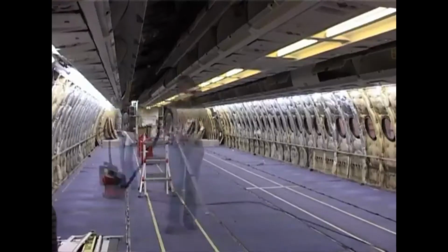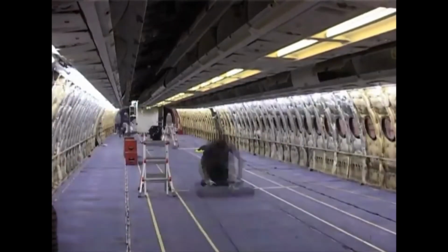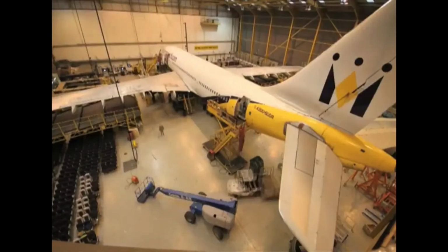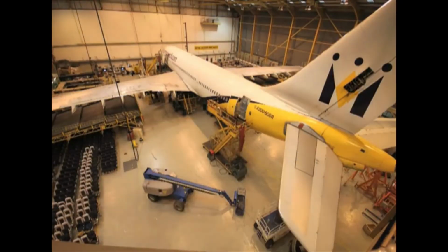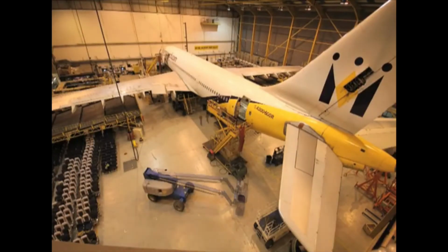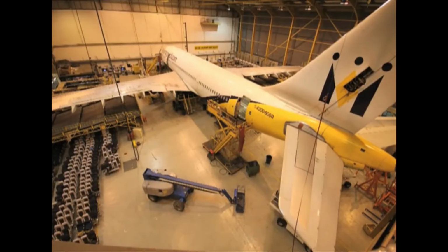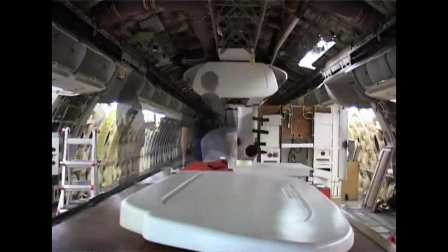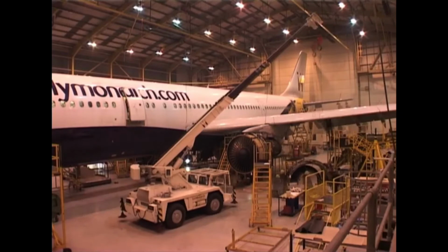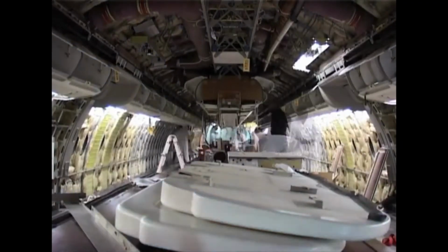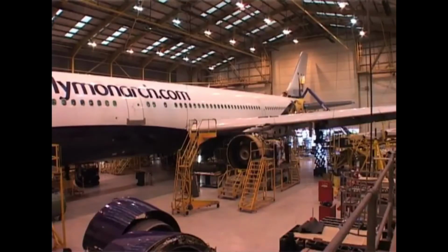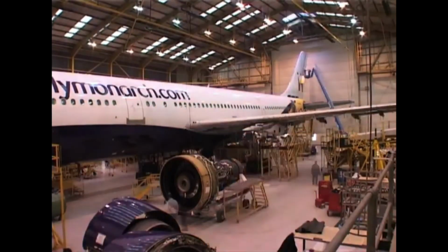When repair of a damaged part is possible, first study the part carefully to fully understand its purpose or function. Strength may be the principal requirement in the repair of certain structures, while others may need entirely different qualities. For example, fuel tanks and floats must be protected against leakage, while cowlings, fairings, and similar parts must have such properties as neat appearance, streamlined shape, and accessibility. The function of any damaged part must be carefully determined to ensure the repair meets the requirements.